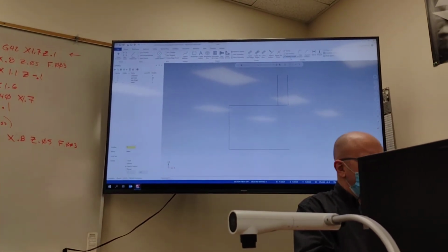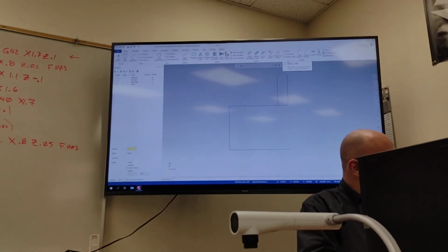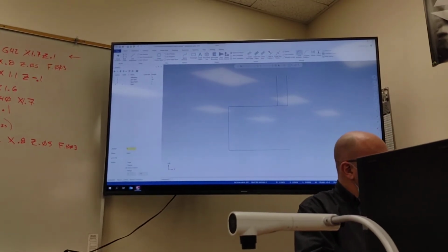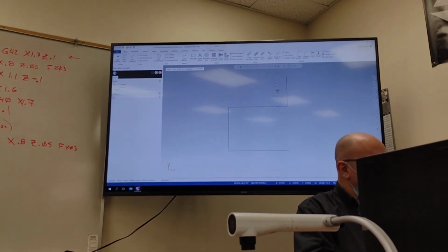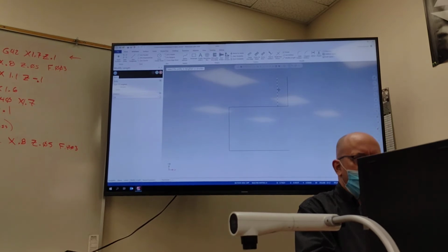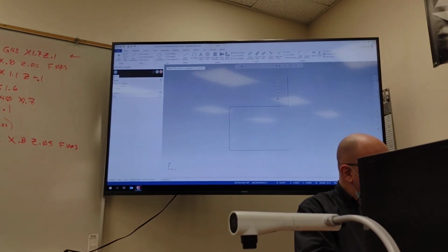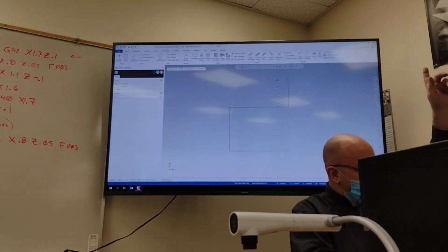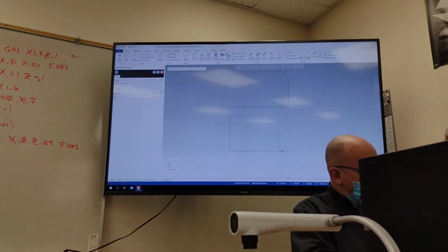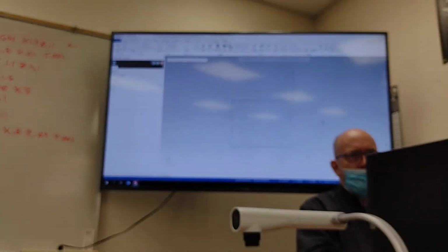And then I want to lengthen it out. I'm going to cut all the way across. This will maybe make more sense in a minute. So modify length. I have an inch. Now this is again where you visualize the center point of your line. If I click to the end closest to it, away from that center line, it's going to go down. If I click up here, it's going to go up. So I'm going to click down. There, it shoots my line across like that.